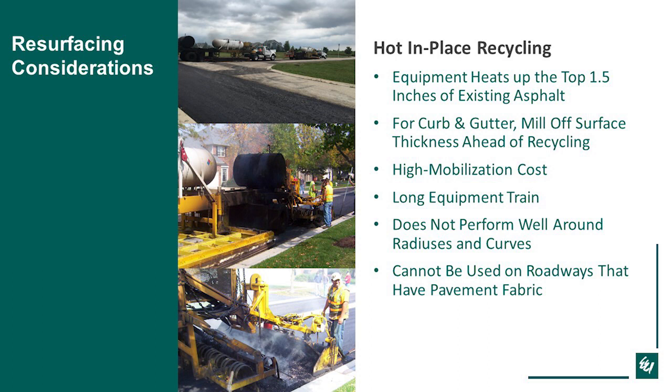it's a little bit difficult to get around really sharp curves, and obviously you can't do it in cul-de-sacs, it has a hard time getting around some radiuses, and then it cannot be used, this is where, as mentioned before, cannot be used on areas that have pavement fabric because the scarifying unit won't be able to tear up the fabric.